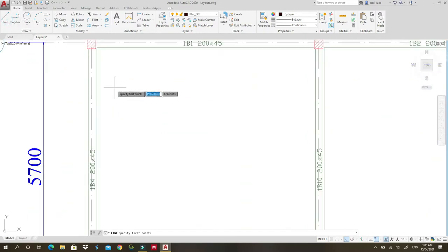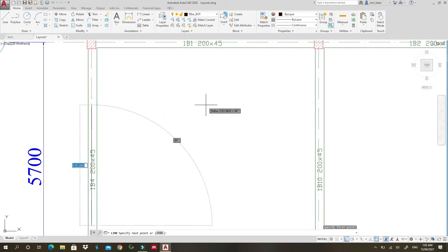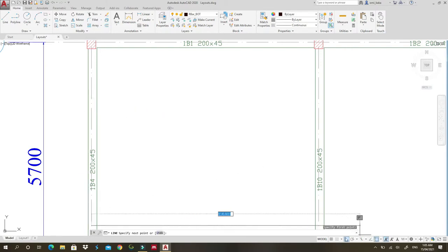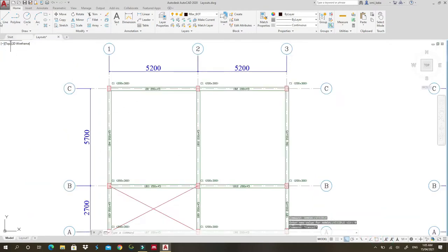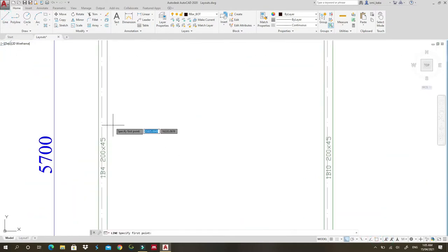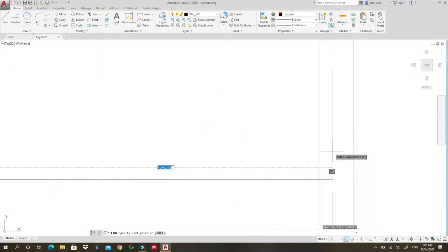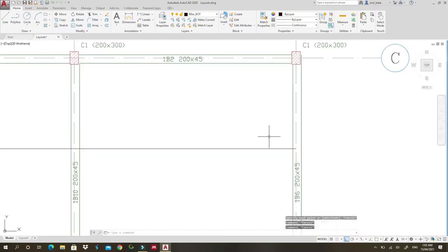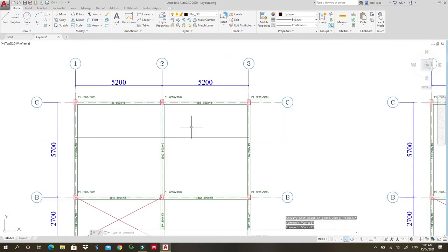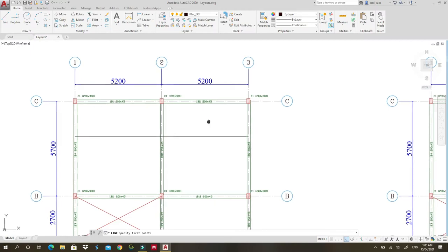So I know that I can just draw my reinforcement right here, and it should go like this. And one tip, always try to use thicker lines for your reinforcement than the labeling lines. The reinforcement should have thicker lines than the labeling lines.